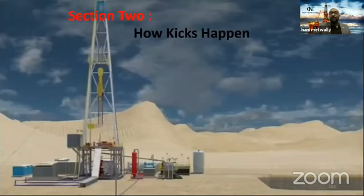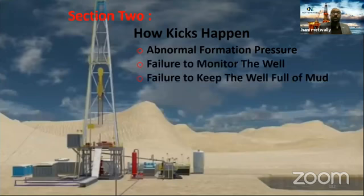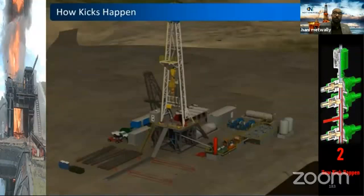Section 2. Now we have a foundation to understand well control. Section 2 will be how kicks happen. It can be due to some reasons, for example, abnormal formation pressure, failure to monitor the well, failure to keep the well full of mud, incorrect fluid density, swabbing while tripping, low circulation. Please don't worry, we will discuss all of this during the section.